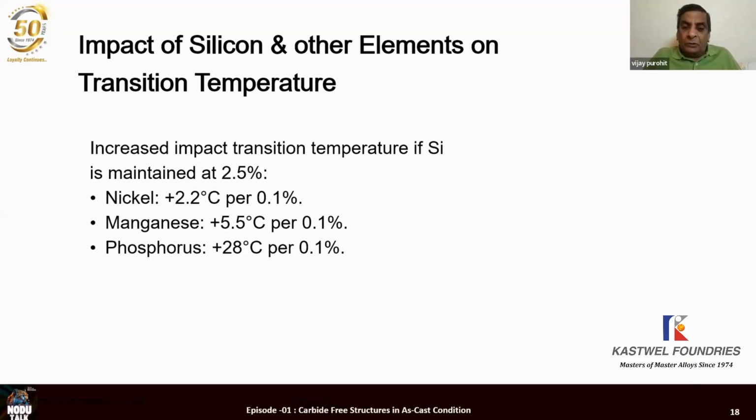as possible. In normal castings, we should try to keep the phosphorus as low as possible, preferably less than 0.004 or at the most 0.005 for thin wall casting, because phosphorus tends to segregate in the cell boundary. We'll speak about it if time permits, and it causes phosphide formation and shrinkage. That's the reason we have to keep the phosphorus low. Next slide, please.